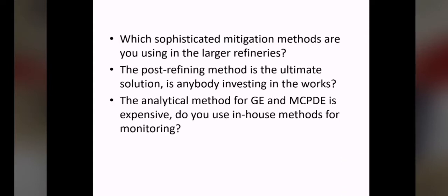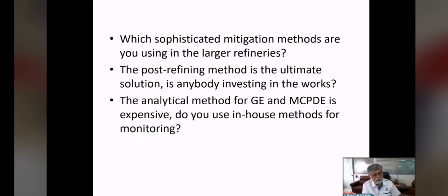Okay, the pre-treatment will probably be the washing. The washing would probably address mainly the 3-MCPD and not all of the GE. For the GE, it looks like it has to be either a post-stripper or an adsorbent, which will be post-treatment. And both methods look like they are viable.